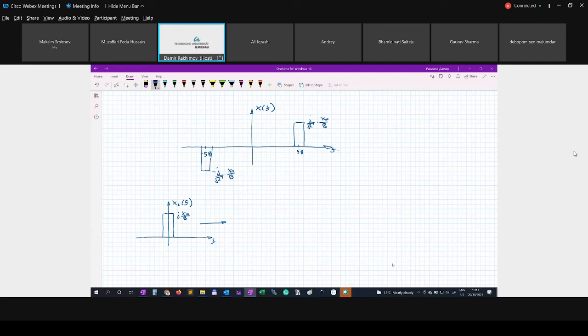So here we're doing a low pass to band pass transformation. Then we change amplitude, we decrease it and divide by square root of 2. So we have j x0 over b times 1 over square root of 2. And then you need to double the number of components.